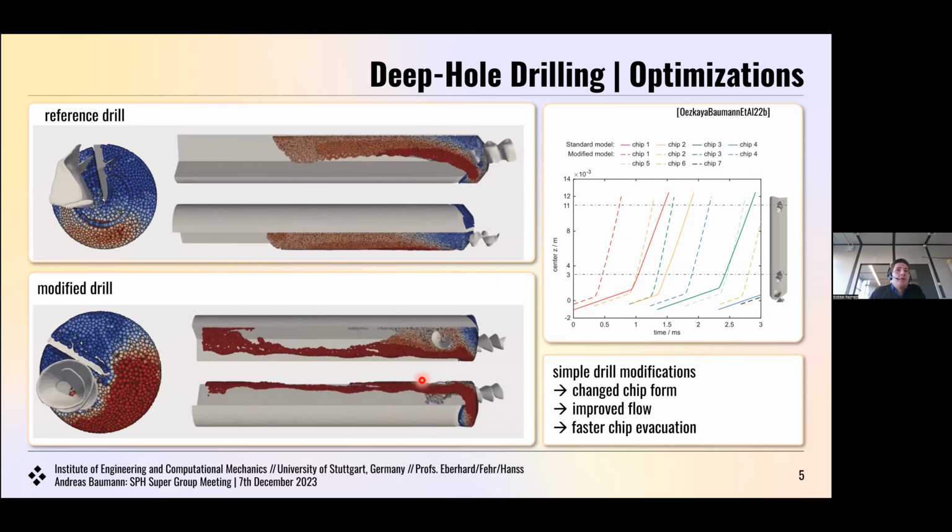So after doing the finite element meshing, we apply our model order reduction. Then we get our elastic multi-body system, which is based on the floating frame of reference. We are coupling this with a standard interface to our particle simulation in the end. And to give you a preview of our current work, what is going to come in the future, we now have our finite element body here on the left, and our simulation here on the right.